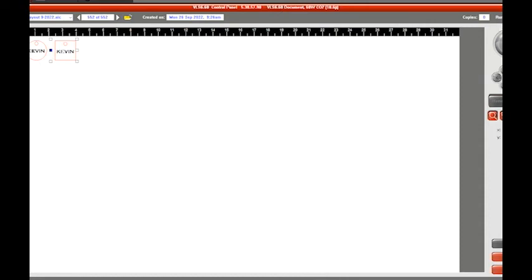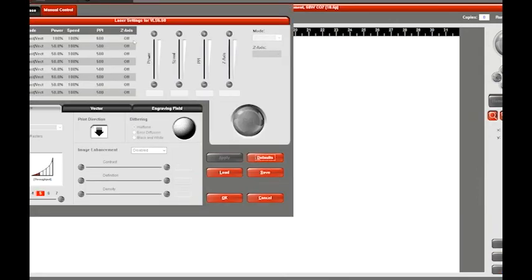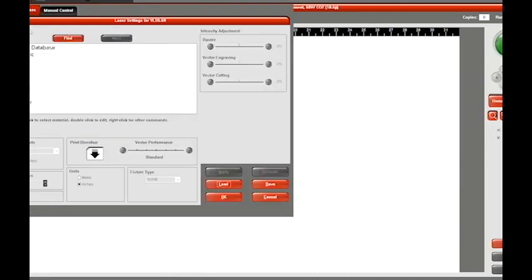So right now at this point, the laser cutter is turned off. So I'm going to turn it on over here in the upper right, activate the engraver, and we'll hear it turn on. So at this point, the laser cutter doesn't know what to do. Basically, if we run this, it'll cut this and it'll engrave it, but it doesn't know the size of the material. So what we need to do first is tell it what's going on. So if we go to Settings, and if we go to Materials Database, these are also presets you can use every time, or you can save your own once you get your materials.